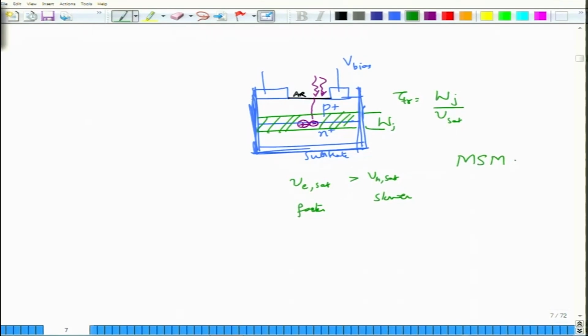They are called metal semiconductor metal photodiodes, okay, where the metal semiconductor and semiconductor metal junctions act like Schottky junctions, which have only majority carriers. Usually this semiconductor is the N type semiconductor, and this is also possible. They also give you very high photocurrent for a given optical input, and they give reasonably large bandwidth as well. But let us get back to this semiconductor based thing.